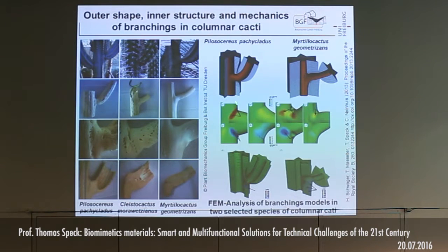And if you look at that, here we have made, this is how the original cactus looks like. This is more or less a kind of engineering simplification. Again here, this is a simplification. And you see in the simplification, without these indentations, without these structures, you always have stress concentrations on top. It's a tension stress, and if you bend the side branch down, the compression stress concentration.